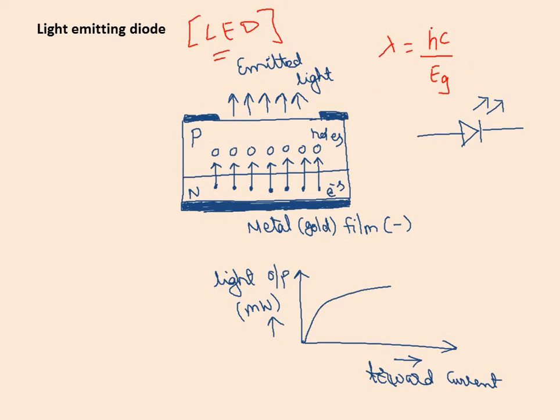So based on choosing that value, we can design or select whatever wavelength we actually need. What does that wavelength refer to? Color only, right? In the visible range it is VIBGYOR. So by choosing the respective energy, we can have the different colors: violet, indigo, blue, green, yellow, orange and red. Beyond these values we also have IR and of course UV. Are we clear with this? So by a proper choice of the band gap and the material, radiation of the desired wavelength can be obtained. But mostly we will always have orange, yellow and green.